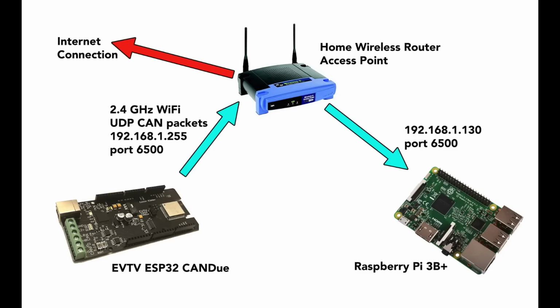What we're experimenting with now is the transmission of CAN packets, which are used in automotive over a 2-wire system, using UDP on the broadcast address of an access point, an AP. The address is whatever your IP address is, with the final number being .255.